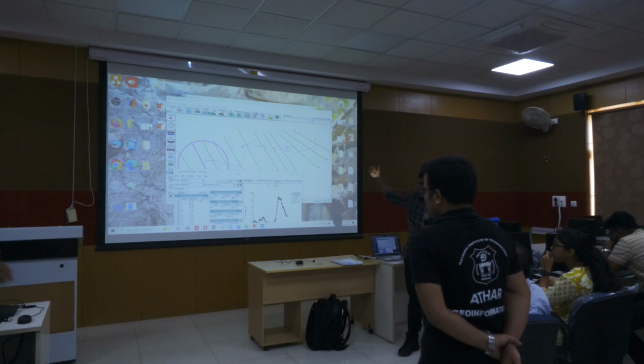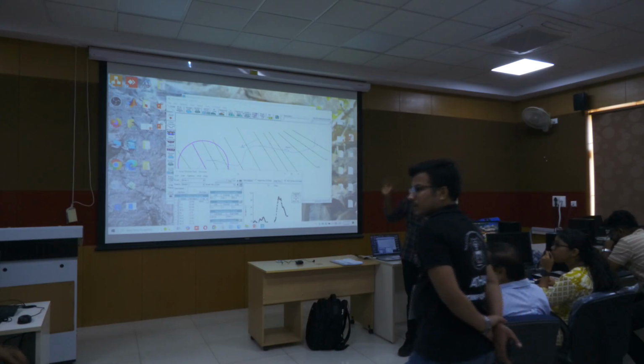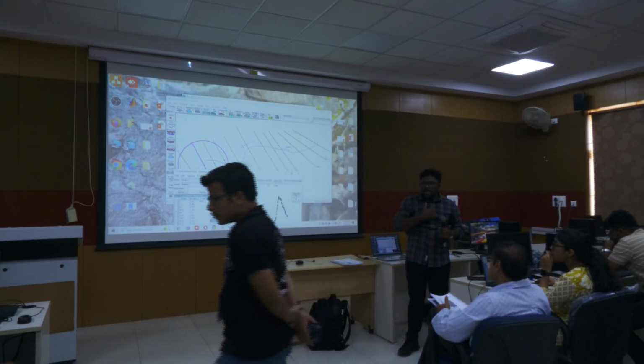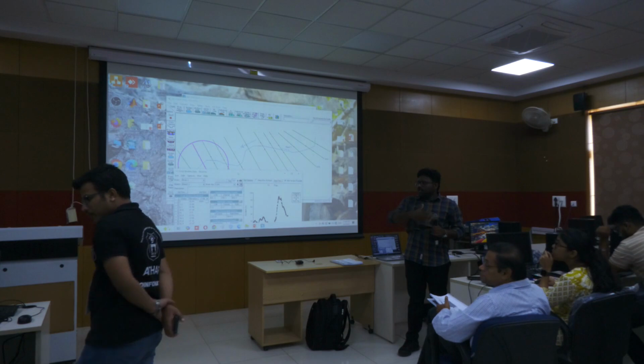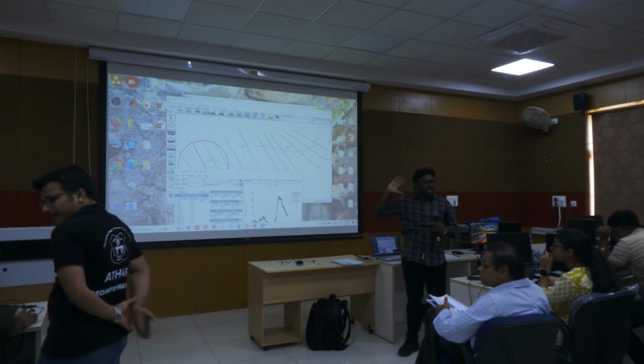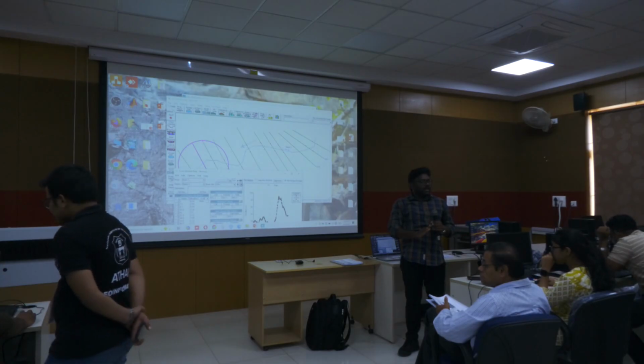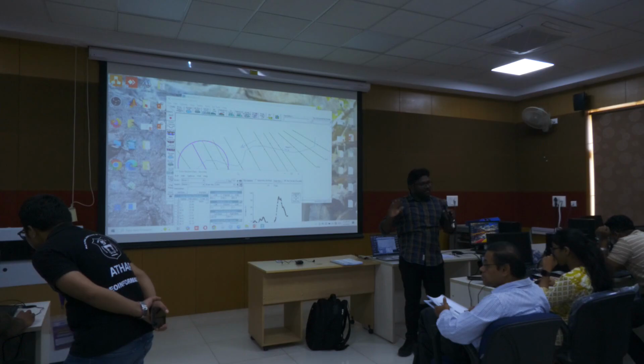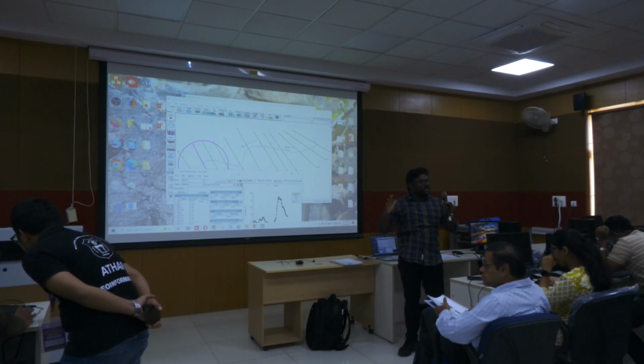In the edit geometry, RAS Mapper. That's why when you are drawing the cross sections, they should intersect with the four lines, and should be drawn from upstream to downstream. Okay, all these rules you should follow. After fixing everything in the geometry data, then only we come here.